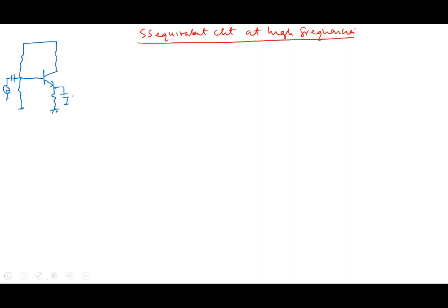Right? Amplifier is here. So let's build our circuit. All right, so let's start with this source here. We have a source. The capacitor, because we are doing high frequency, we will consider as short. As usual, we have this R1, R2. R1, R2 will become in parallel, so we'll put here R1 parallel R2.